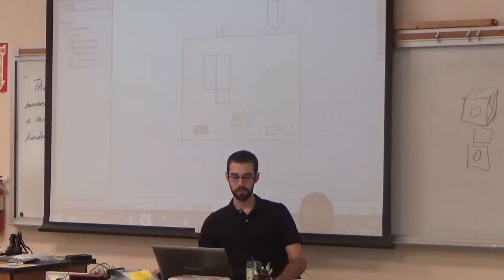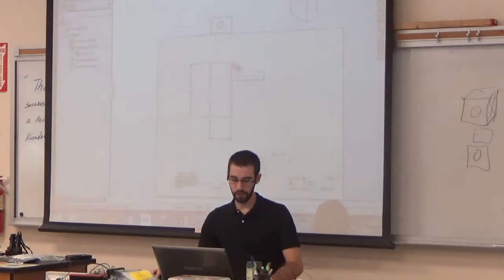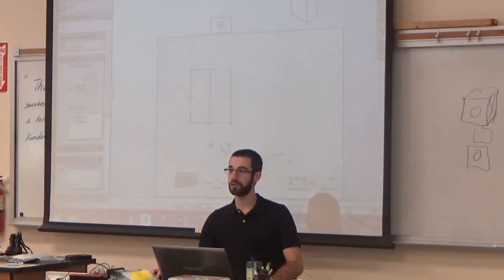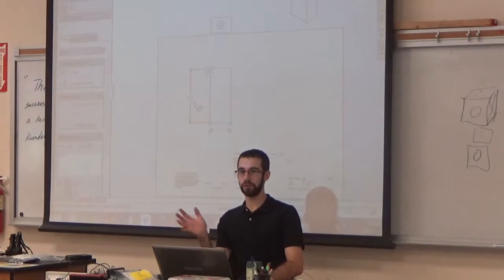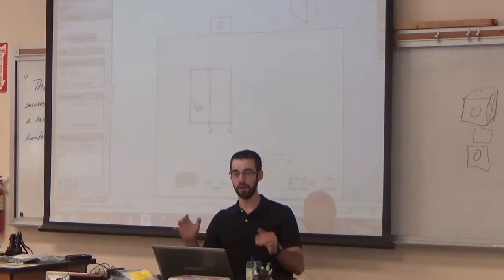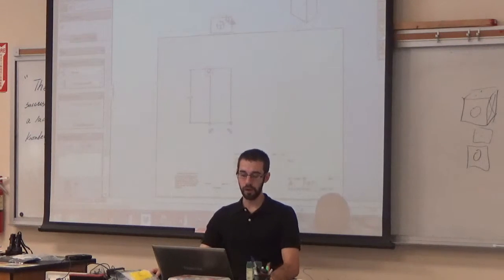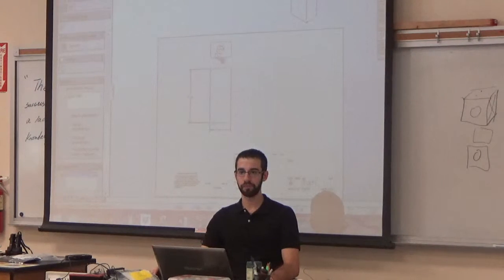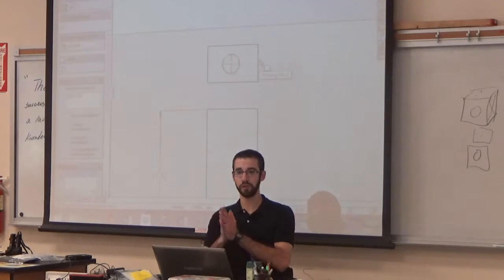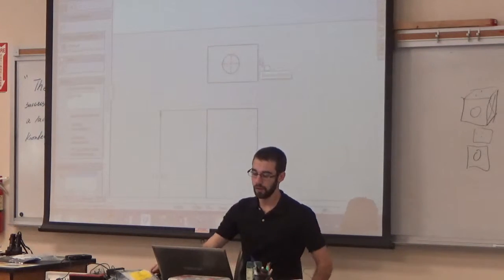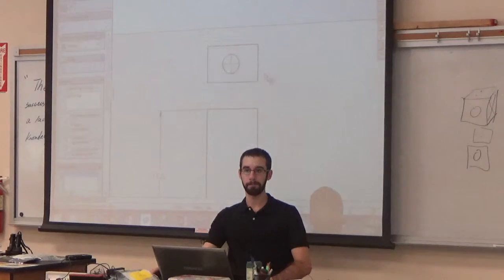Because we have to define the circle. The circle and the... On the top, because we haven't constrained anything there, so. Right. So yeah, typically in your parts you're going to constrain stuff to these dimensions. So that 11.32, I'm going to constrain when I did my part. Right here, it's not that important. And so you will notice when I did the circle, crosshairs popped up on it. And that's so we can dimension to the center of the circle. So what would I dimension on here?